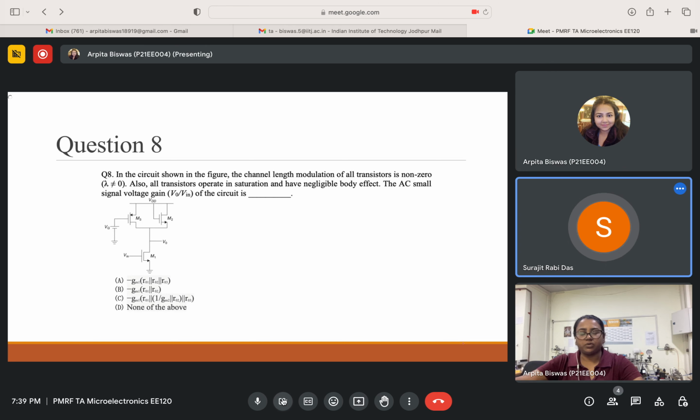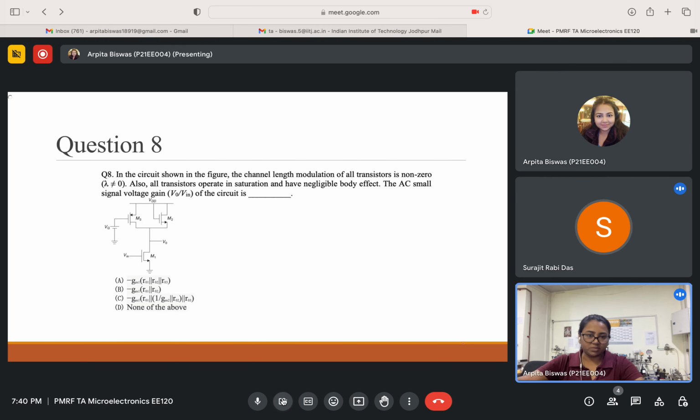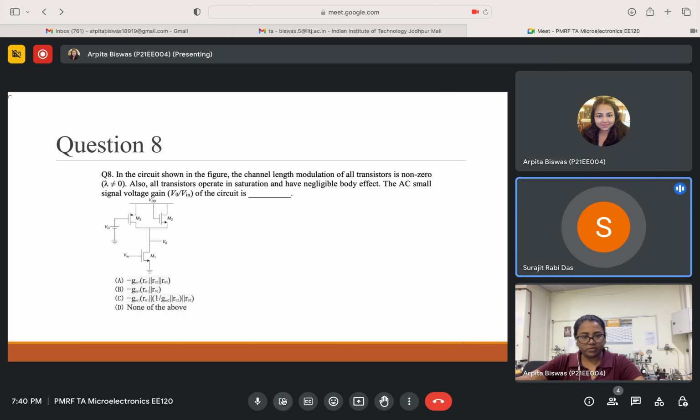If you want to grow some oxide, there are different types of oxidation processes. Then there are different types of deposition, like CVD, chemical vapor deposition, and physical vapor deposition techniques. This is the whole device fabrication. I am now working on a 2D material based biosensor, so we use CVD to grow this 2D material. After that we prepare the contacts, and in that case we use PVD techniques, physical vapor deposition, like thermal evaporation system, E-beam, sputtering, and so on.